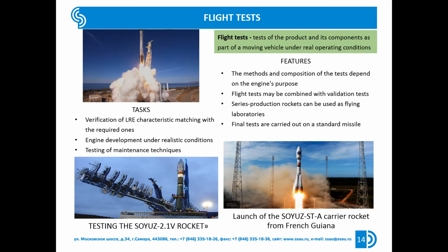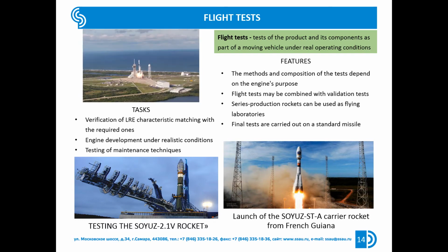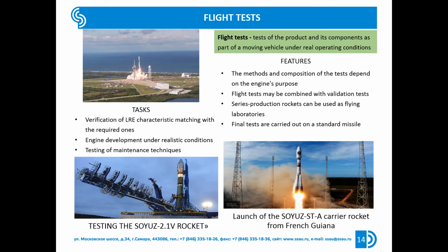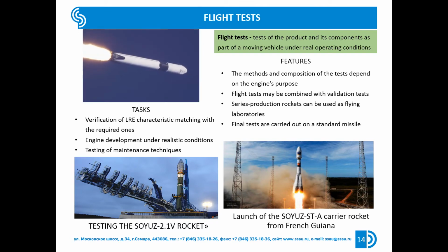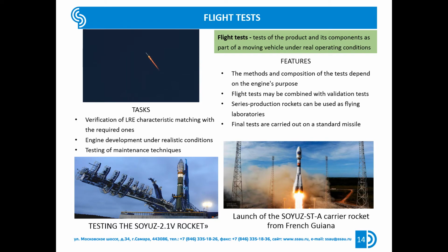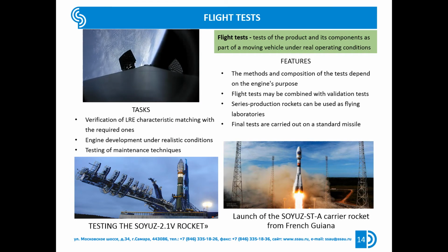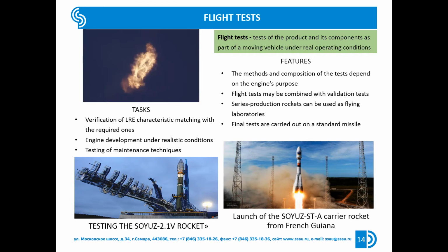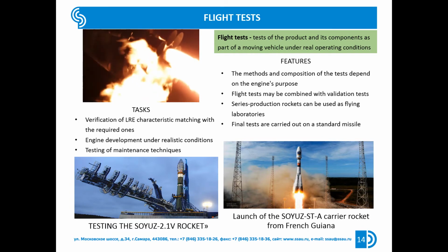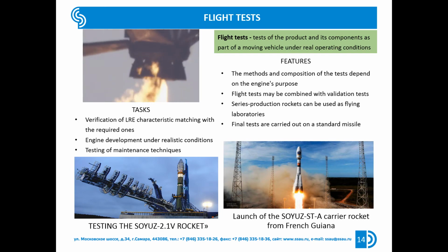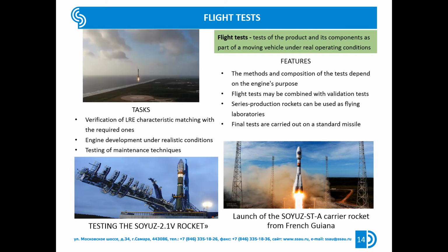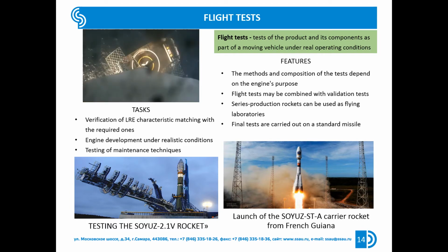Flight tests of a newly developed or modified LPRE conducted to check its performance against technical requirements, during which additional development of the LPRE can be carried out, are called flight design tests. Flight design procedures and their scope can vary significantly. They depend on a number of factors, most importantly the purpose of the test engine and the cost of the flight test. For example, flight design tests of LPREs for relatively small unmanned flying vehicles may be initiated early in the program development phase to identify design weaknesses.